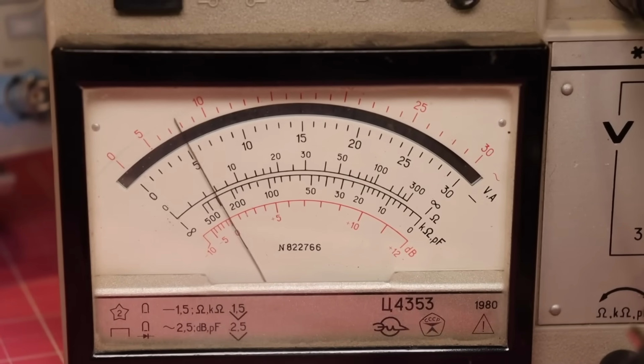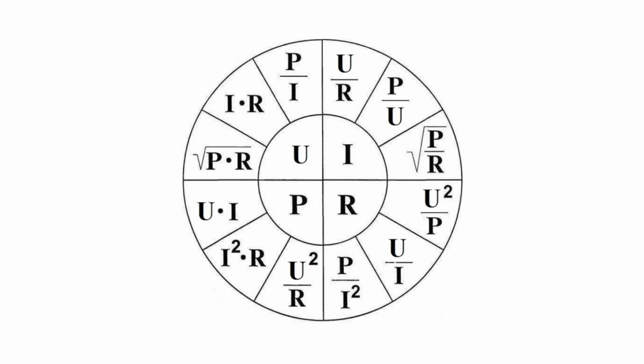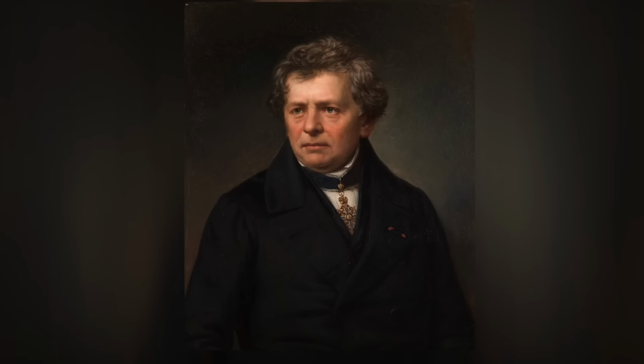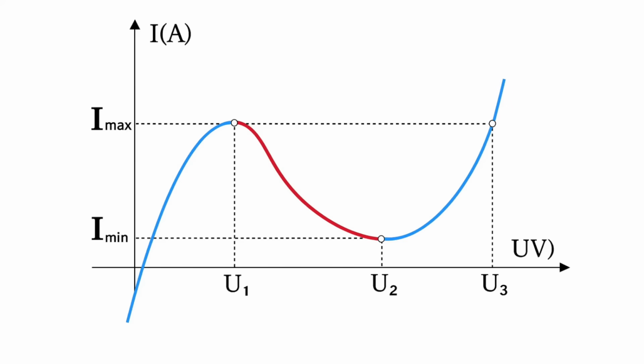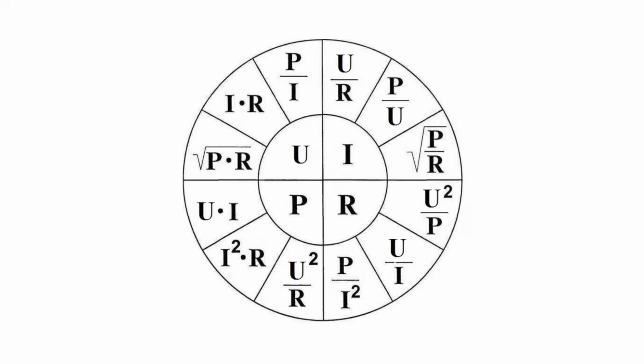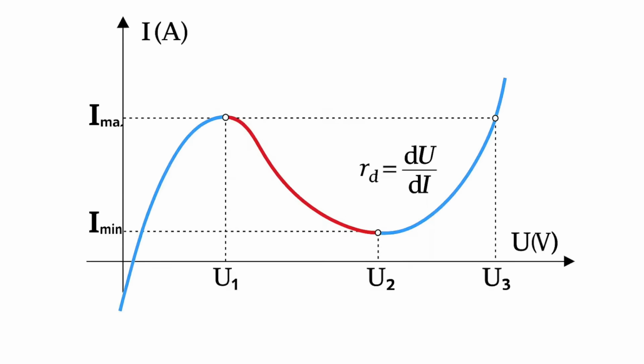So does this process contradict Ohm's law, or even disprove it entirely? I would really like to say that there's no way around Ohm. And here, within a certain voltage range, we are dealing with differential resistance, which can actually be less than zero, but Ohm's law is still not violated and continues to describe the relationship between current and voltage. But there are some nuances here.